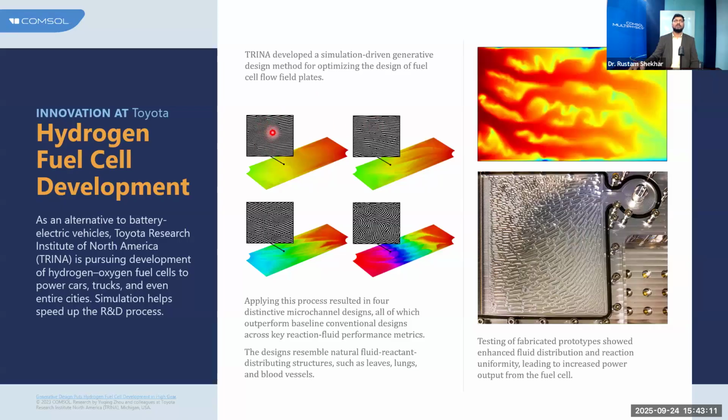Different designs give you different current distribution in your fuel cell systems. If we go for this kind of design, we may have better distribution of our fuel. The goal was to get a uniform distribution of fuel, which will lead to uniform current generation, and that may resolve multiple problems which may occur in our fuel cell systems.